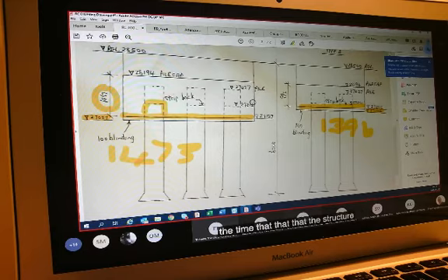So this concrete would, in most instances, be exposed for the duration that the structure would be standing there. So in most instances, we would measure smooth formwork to the sides of the pile caps.